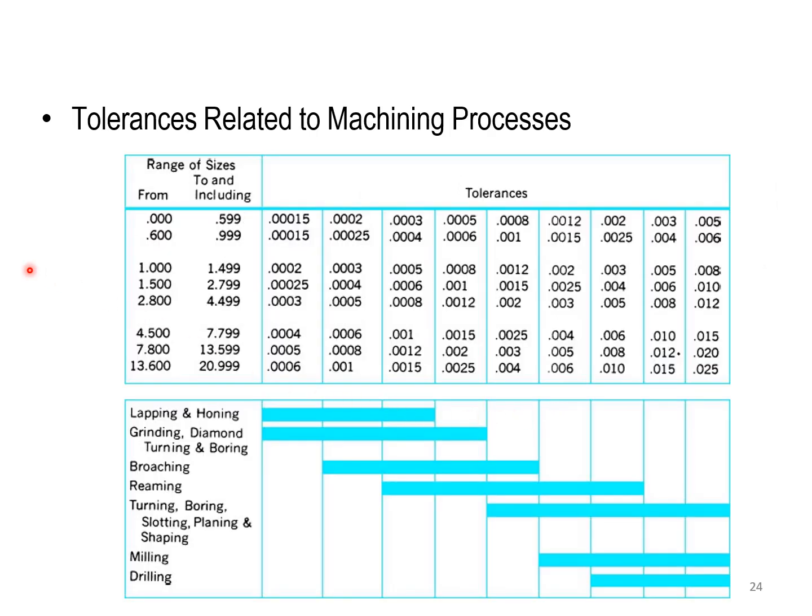Now, the tolerance-related machining processes. Of course, different machining processes are going to give you different tolerances, as we mentioned earlier. The better tolerances you have, the higher the cost of the machine is going to be. So these are the ranges of the tolerances, and these are the sizes included. So you can see, for example, again with my example of the 1 inch, I'm going to come to this one. And the tolerance I would like to have is something like, let's say, 2 in 1000. So I'm going to come to this one.